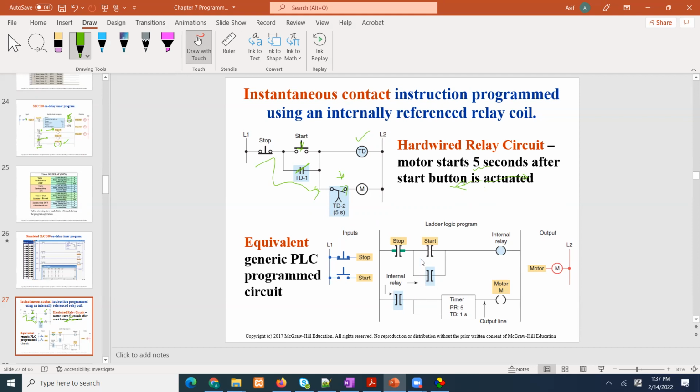And this is the PLC program. So we got a stop, start right here. This internal relay is maintained. Then this internal relay, and then we got the timer, and then we got this guy. We haven't talked about internal relay. We can use B3, which you guys will see as we go on. But we can do it if you guys want. Let's make this guy quick.